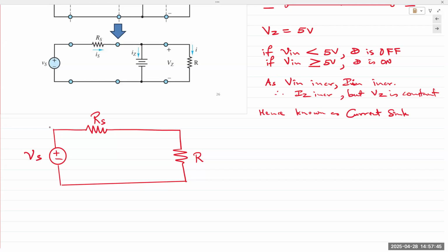It remains the same. Series circuit current remains the same. There's only one road around the block. If you start driving from voltage Vs, you only have one road to go around the block. Current remains the same. However, voltage gets divided. So it's a voltage divider circuit. A parallel circuit of resistors is a current divider circuit. Series connection of resistors is a voltage divider circuit.